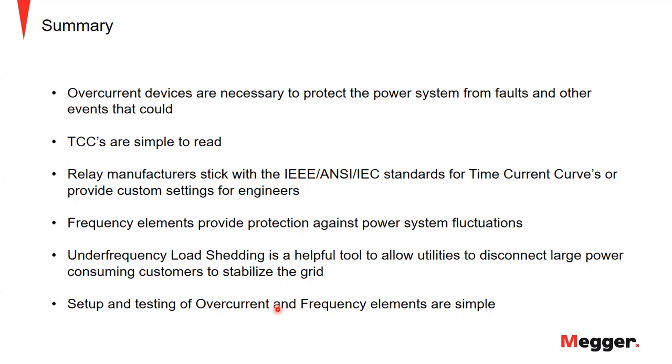And then the relay manufacturers always have the same standard. They go by specific standards, but also, like I was saying earlier, they provide custom settings. So you can create your own type of inverse time curve in case the ones that they have are not reasonable enough for you to use for your coordination.